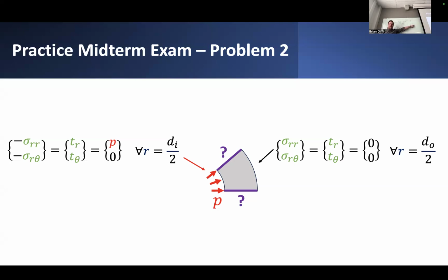So minus quantity for the inward normal multiplied by these stress components gives us apparent negative values for these tractions. That's precisely why we have these minus signs included here, if you were to go through establishing these relationships using Cauchy's stress theorem.